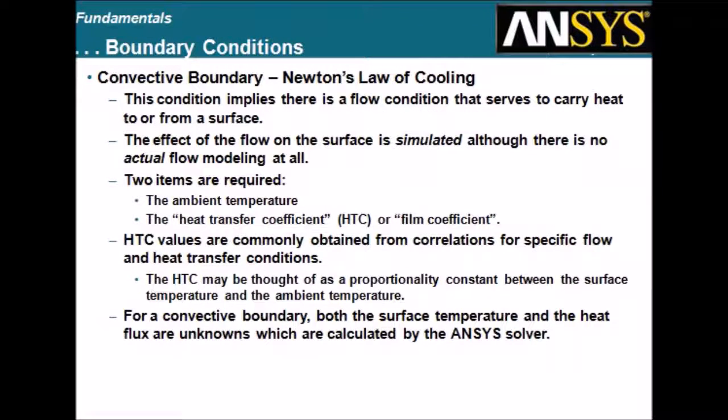Convective boundary, Newton's law of cooling. This condition implies there is a flow condition that serves to carry heat to or from a surface. The effect of the flow on the surface is simulated although there is no actual flow modeling at all. Two items are required: the ambient temperature and the heat transfer coefficient, HTC, or film coefficient.